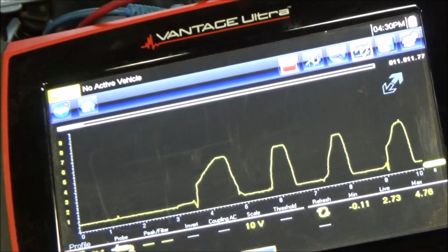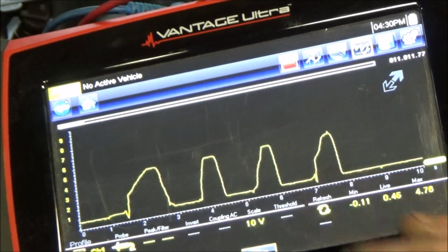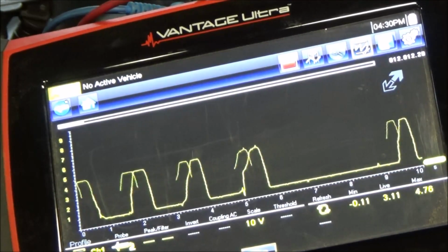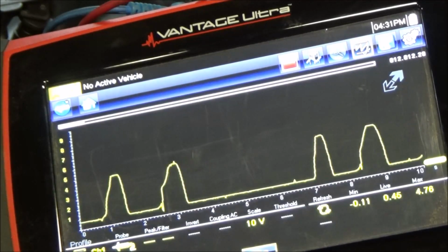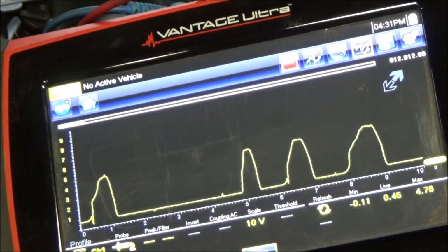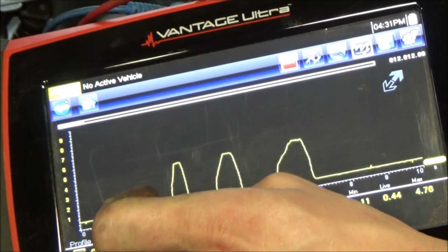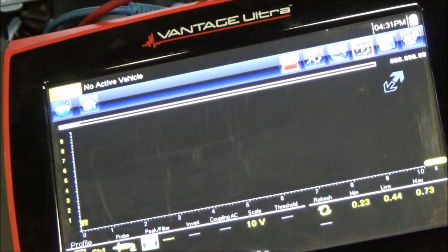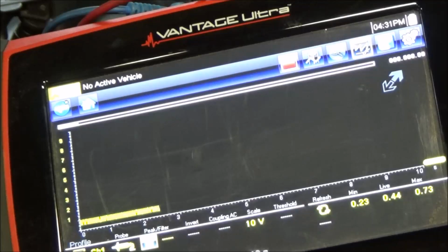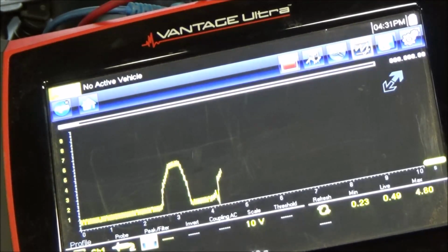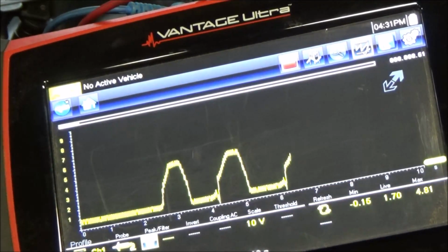And you can see if you move it quick enough, we can still even see that glitch is there. You see that bouncing across the screen. If we were to put peak detect on, I'm sure that we would capture this glitch a lot better every time. So we're on peak detect now here, guys. And we saw one there.